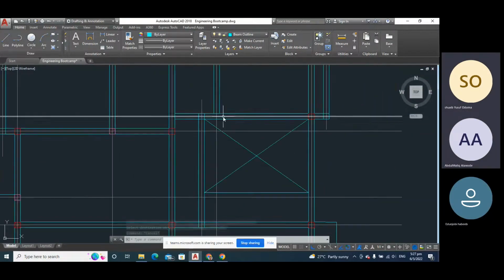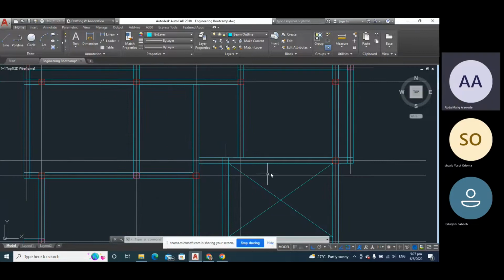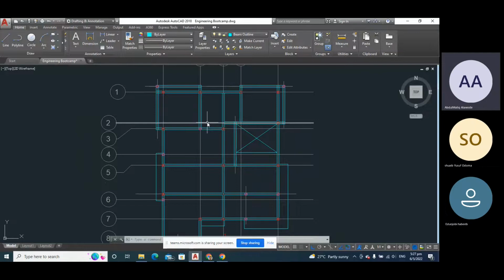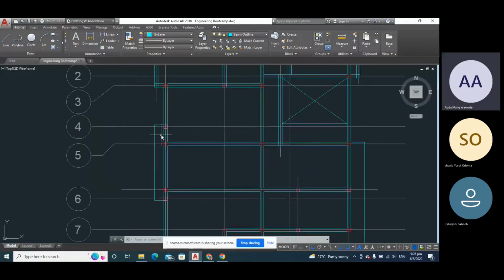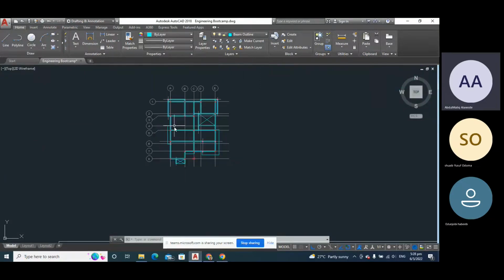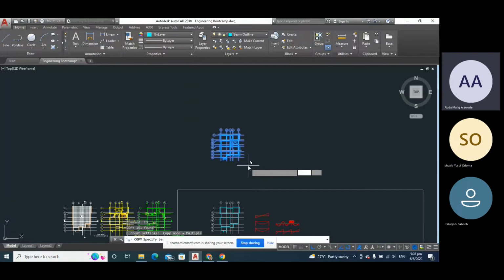Did we create that you have not merged the property? None. Now the next thing that I always prefer to do is my slab outline. Because when you are using ProtaStructure, as I've said, it deals with grid line. So I always prefer to convert my slab outline to grid line also. To do that, I always prefer to have a copy of this drawing, because this is what I will later edit to finish work.